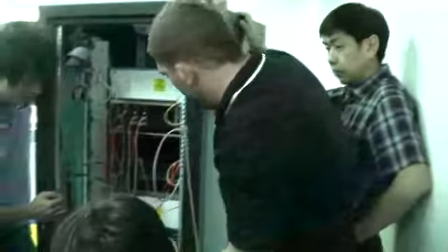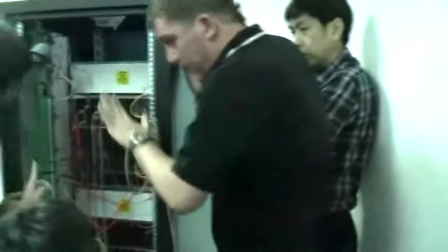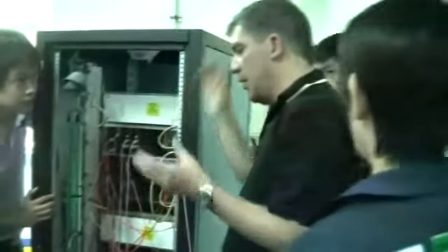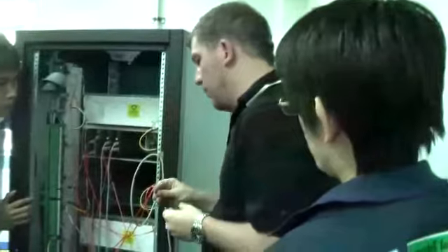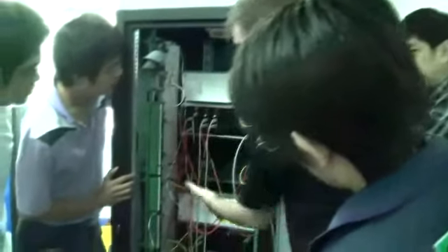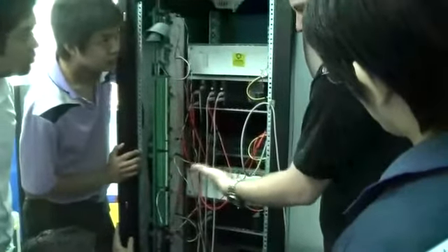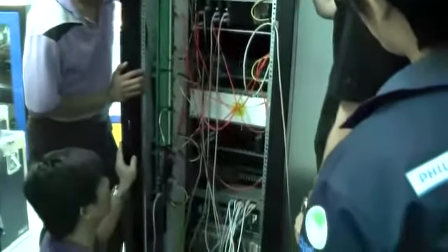In the GTDO card, it is a dry contact only, right? No, the dry contact ones are on the front, because here we're wetting the contact. We're wetting it with 5 volts. Yeah, 5 volts. So when we do relay testing, a relay contact is a dry contact, right? Closed or open. Yeah. So typically we use the front panel, but we can use this, but we have to supply a voltage, the 5 volts. Oh. Yeah. Okay.